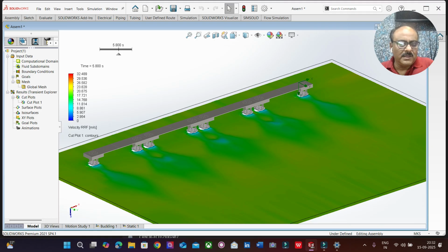Let's imagine that on the bridge deck there is going to be a road. Okay, it's a double lane road. There are going to be huge rolling loads, braking loads, traction loads, and all those loads are going to come on the superstructure. These kinds of loads are going to be taken by the expansion joints as well as the bottom PTFE bearings or elastomeric bearings.